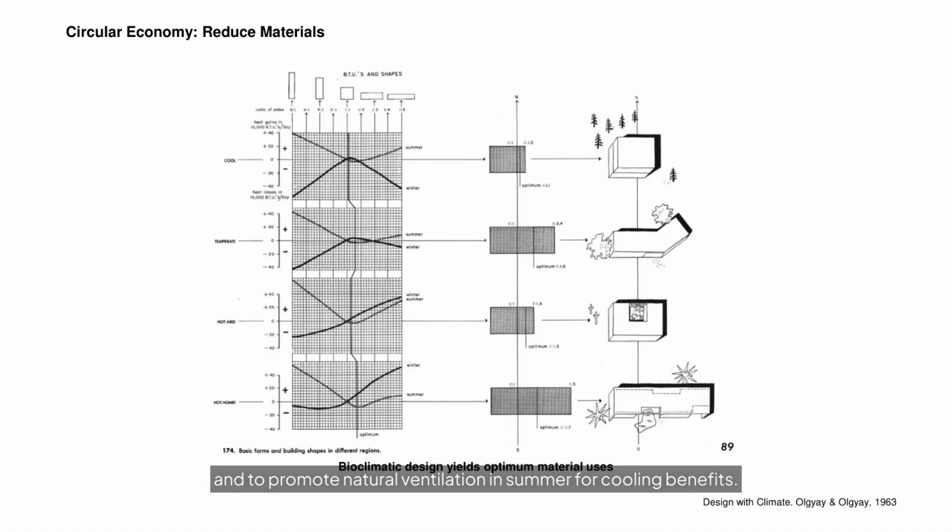In a hot, dry climate, the footprint ratio is 1 to 1.3, and the building integrates courtyards for evaporative cooling. In a hot, humid climate, the footprint is 1 to 1.7, more elongated than the one located in the hot, dry climate. Windows are protected with shading devices, and the building mass is articulated to augment self-shading.